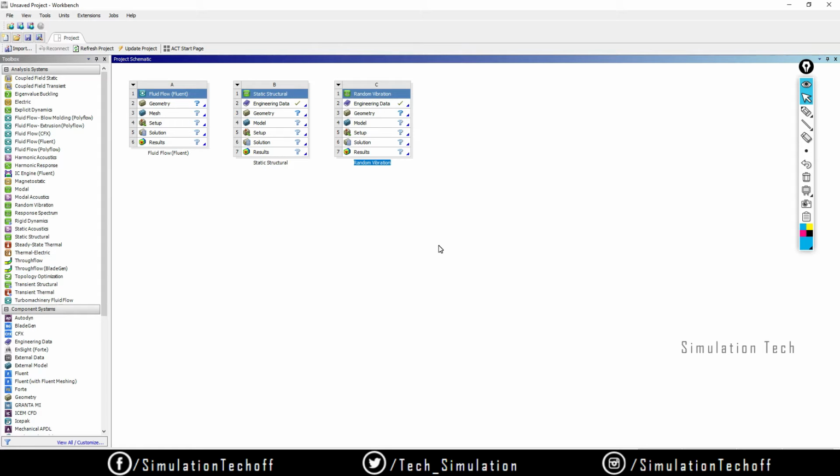Okay, so while we solve an Ansys Workbench problem, we have a pattern, right? First we need to define the engineering data. Once it is defined, we move on to the next step, geometry creation. Once the geometry is created, I'll move on to the next step, boundary condition creation. So the creation of meshing, then assigning fixed supports and then loads, and we're looking for post-processing, that is results: what will be the maximum stress and minimum stress. So this is the followed sequence of steps.